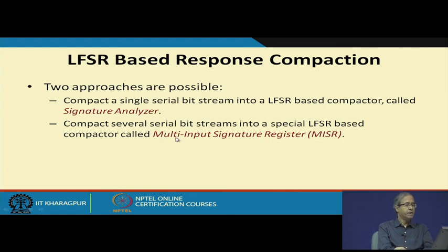Now, when I talk about response compaction, and here again we are using LFSR, two broad approaches are possible. One where we compact a single serial bit stream into a compactor, this is called signature analysis, and the hardware is called signature analyzer. As an alternative, several serial bit streams can be compacted, that is called multi input signature register. I am just showing you schematically.